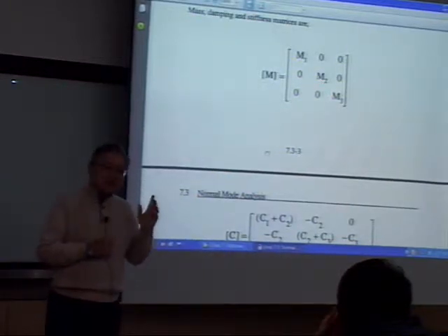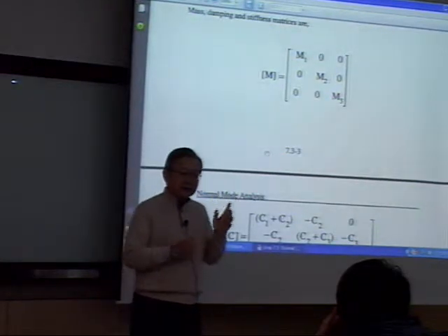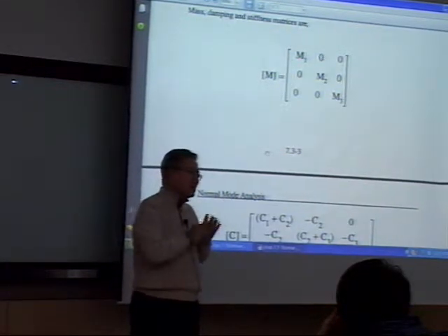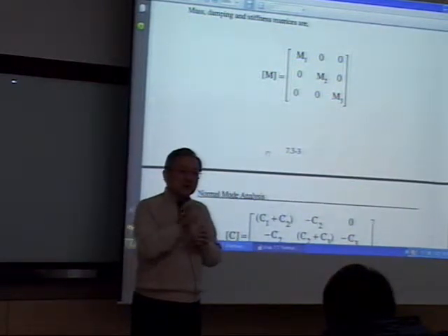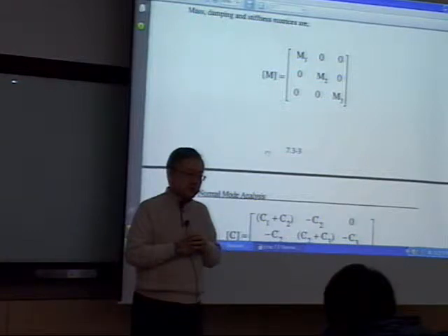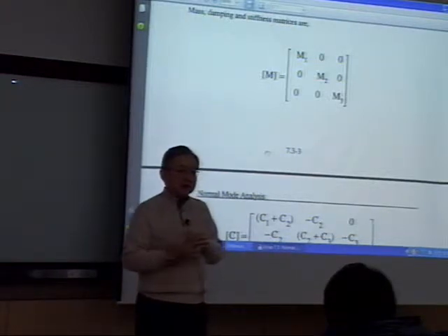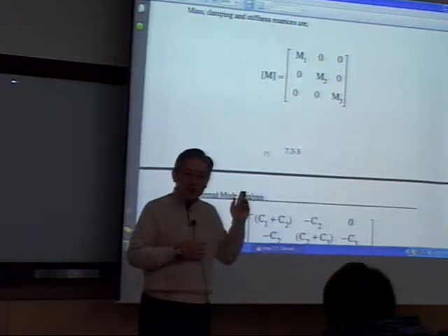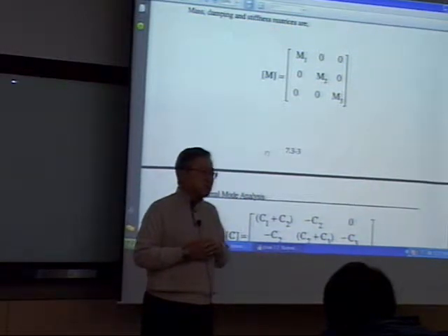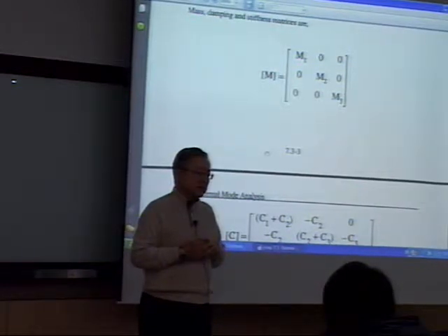But in this case, this is really discrete mass, 3 lumped masses there. So always you will have the diagonal mass matrix. And any commercial code, Dynacode, Nastran, ANSYS, Abaqus, is all dealing with the diagonal mass matrix, which makes computation a lot easier.